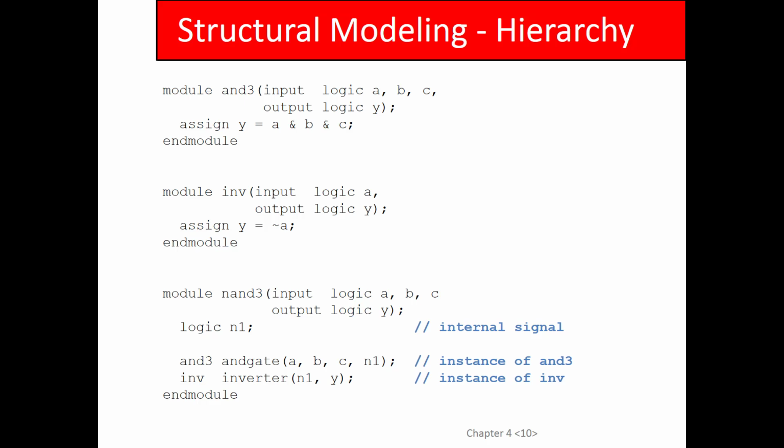Any questions about that? Okay, so this is behavioral. Why? Because there's a truth table, Boolean logic. Behavioral. This is structural code. Structural because there's no behavior in here. I just took two gates and connected them together. So this is structural code. Like I said, most code you write will look like this.